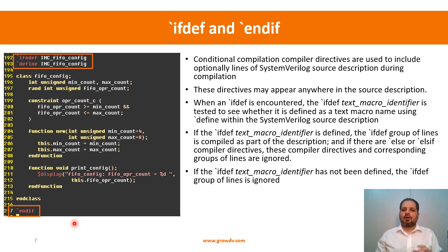While you are instancing, you can use `ifdef and say, if this type of configuration, then some additional signals get included, and then `else, some other signals get included. When you are compiling your overall testbench, you define what type of DUT configuration, and depending on that it will figure out which additional signals to include. So you can use these ifdefs anywhere you want to conditionally include some part of the code during the compile. This is happening at compile time, not at runtime. Just at the point where you are compiling, it gets included. During runtime you cannot make any changes.